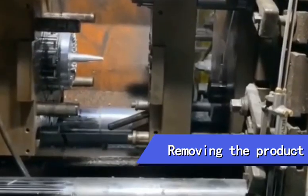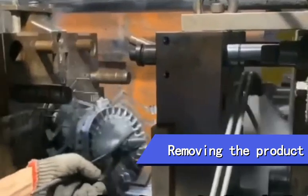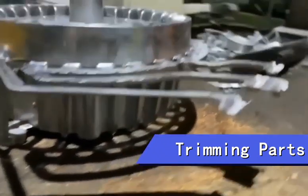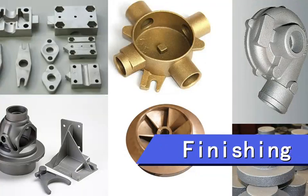Removing the product. Once the metal has cooled and solidified, the casting product is removed from the die. Trimming parts. The individual parts are then separated from the casting, and any excess material is removed. Finishing. Depending on the desired finish, the parts may require additional machining, polishing, or other finishing processes.